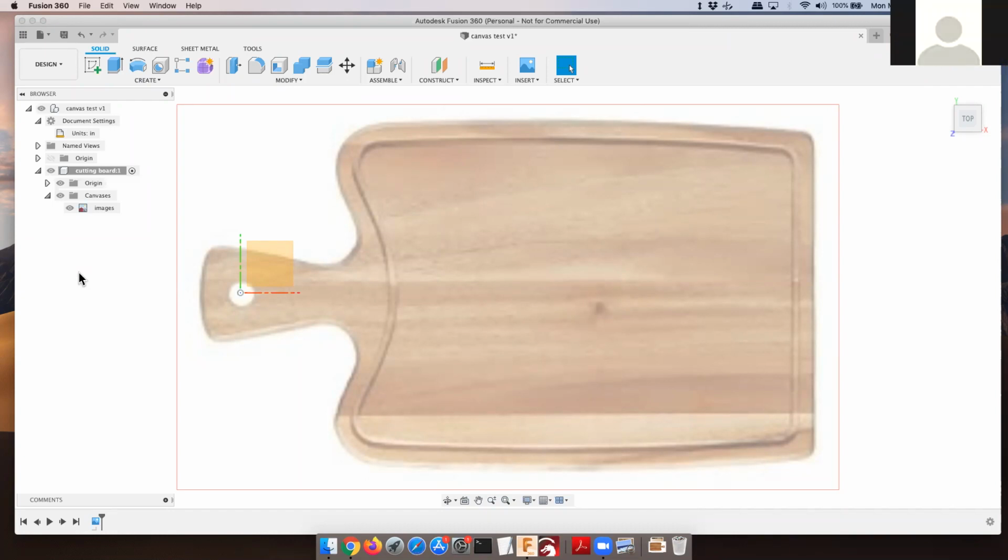Okay. The question is raised is where you put it. If you are keeping symmetry or being able to mirror about an axis, so you only have to design half of the board, are you at that stage right now or thinking about putting your origin in a place where you can do those other modifications? Right. So what's important there is that the red line here, the x-axis, is on the line of symmetry of the board. That's the important part. Where it moves in x, y really isn't that critical. Okay.